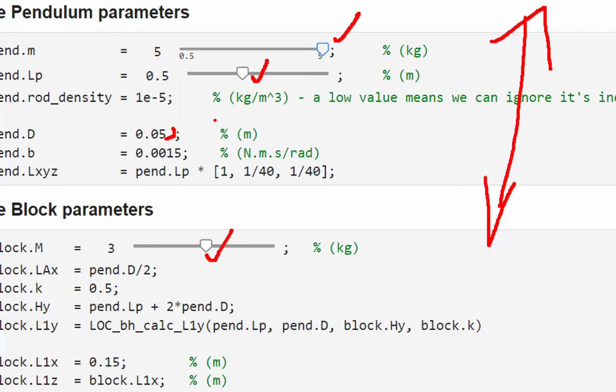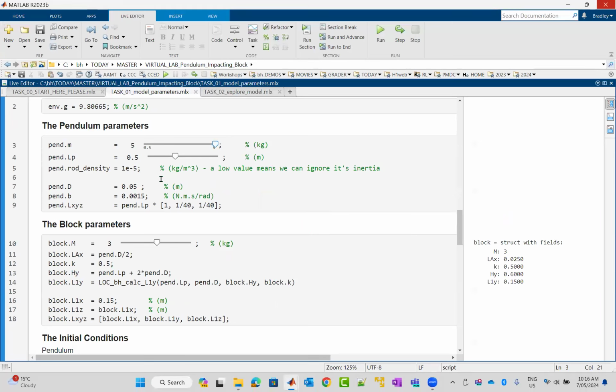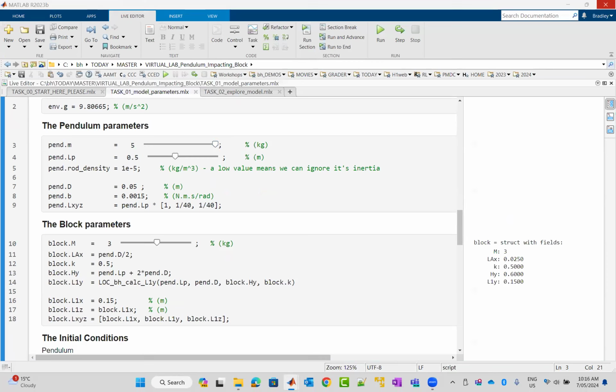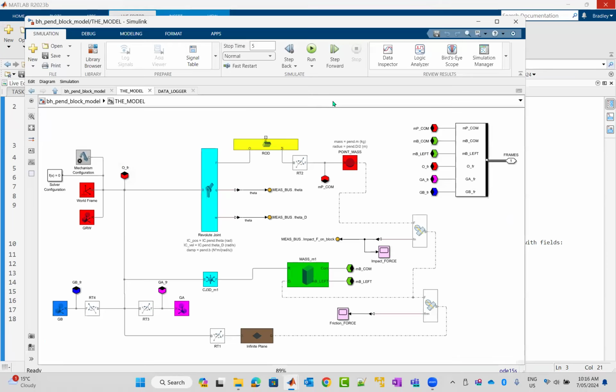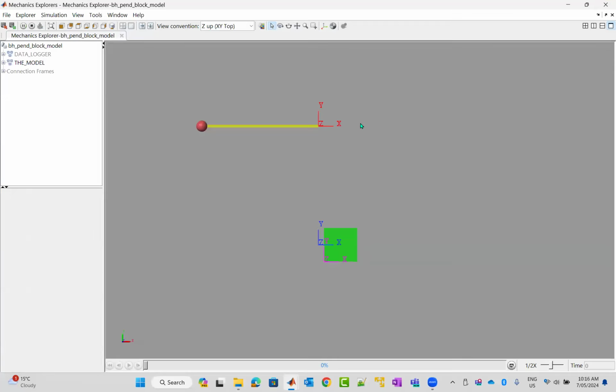But with these interactive widgets, the mere fact that you're changing them by moving the slider, that automatically runs the section that the widget is in. Alrighty. So that looks good. Now we can sort of bring our Simulink file back on the screen, and let's run it. So as you did before, look for that circular green run button in your Simulink file and click it.